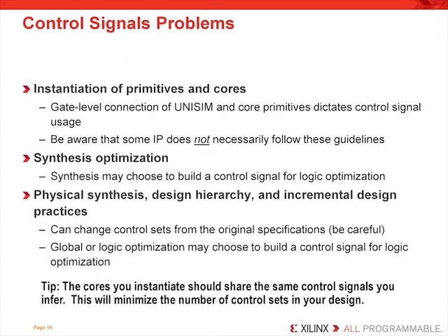So since these rules are not obvious, it is important to plan your control signal usage. But there are a couple of other things to keep in mind. First, when planning your control signal usage for your flip-flops, keep in mind that the instantiation of cores will also add additional control signals to your design. So try to share these instantiated control signals as well with your HDL code.